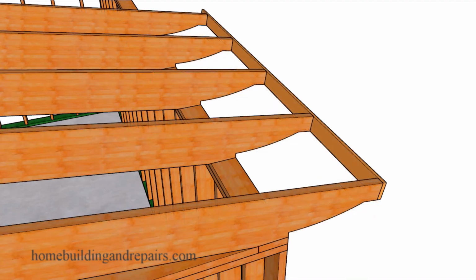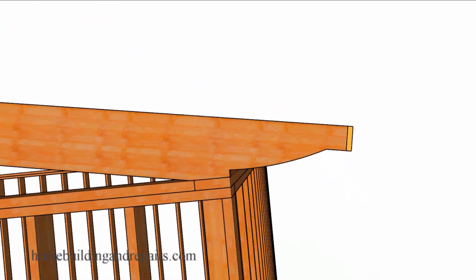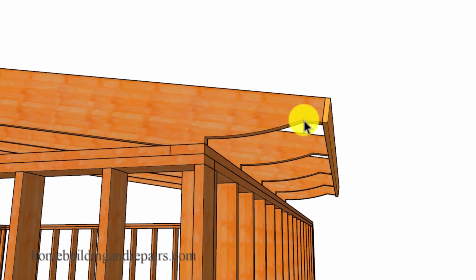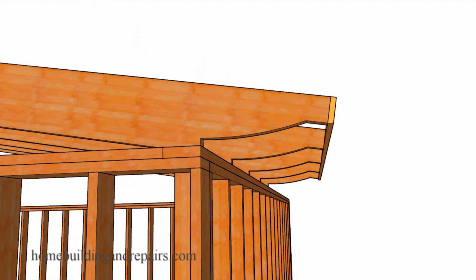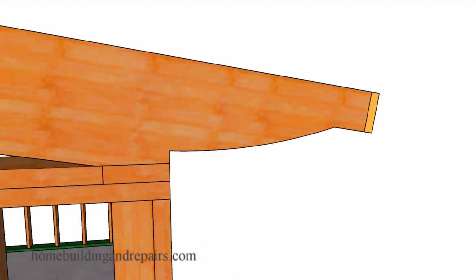And if the rafters are a little wider, you can always put a little design on the end of the rafter tails. And of course, this design here would create a stronger roof overhang than it would if you ripped this down to 3.5 inches here. However, this wouldn't be something that's going to save a home builder money because this could be labor intensive here.